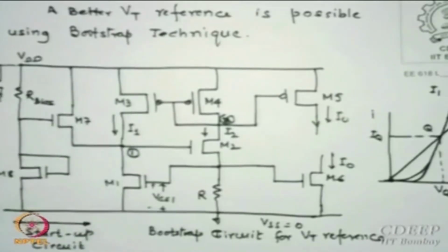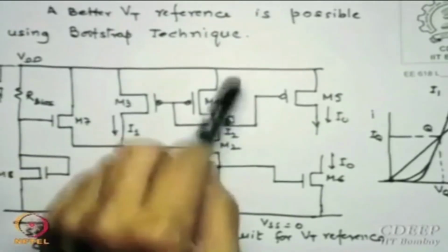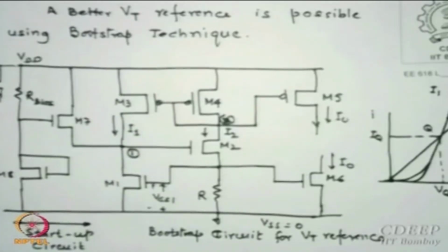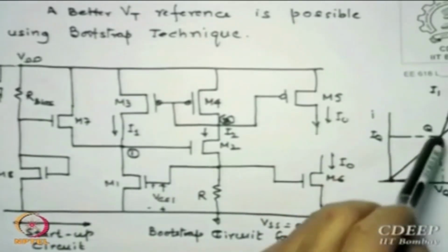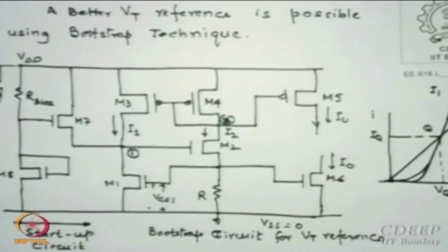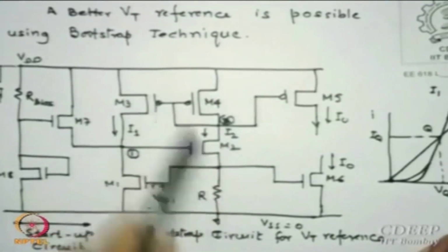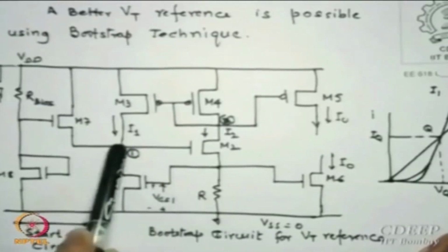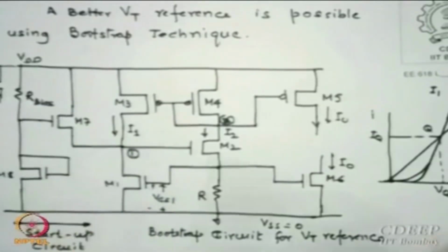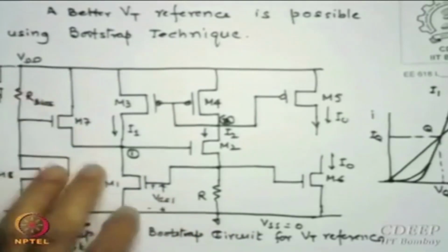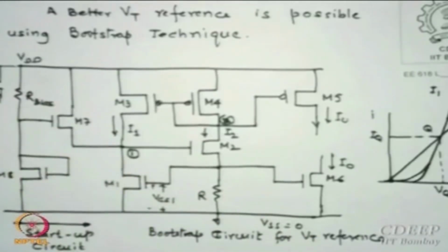Once M7 switches off, now I1 and I2, where feedback paths are taken care of, whenever they become equal, you will reach the stable point. So is that correct? Yes. Let us say initially this was at 0, when both currents are 0, so this is 0. So there is a VGS sufficiently high because only one diode drop was taken out of it. So VGS was larger than VT for M7, is that correct? So M7 conducts, meaning it pushes the current into M1.